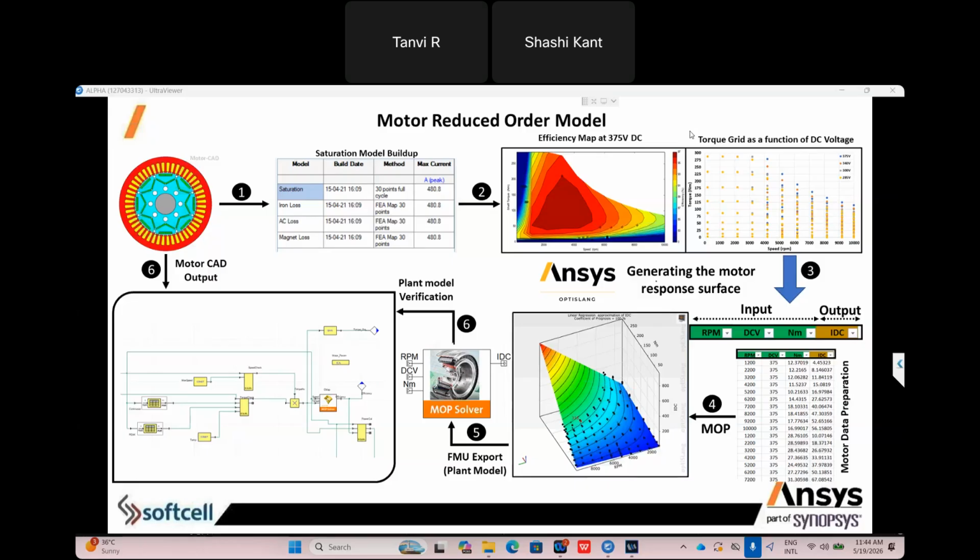So which type of losses will happen, and how it will respond. If you want to understand the temperature generation and noise generation, also NVH, that can also be captured. Maybe the motor is getting very hot, so we need to add some coolant process or coolant mechanism to cool it. That can also be done very fast. So for specific motor development, we have Ansys Motor-CAD and other Ansys solutions which can help you develop a motor from the very beginning stage.